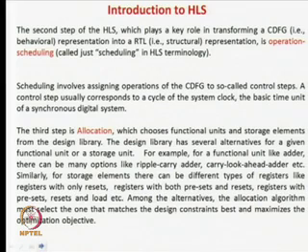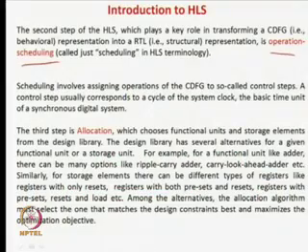Then we go for operation scheduling. As I already told you, what do you mean by operation scheduling? In a control and data flow graph we have some operation nodes. Each of the operation nodes we should assign to some time step, that is, this operation will be done in time step 1, this will be done in time step 2, and so forth. That is called operation scheduling, or scheduling in high level synthesis terminology. We will see the actual formulation of the problem in detail. This is the second step.